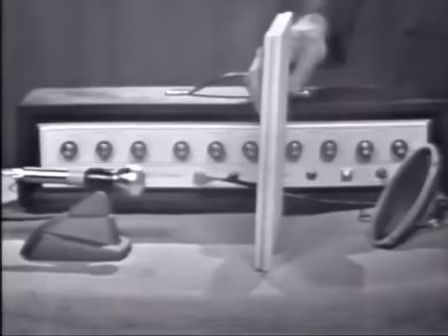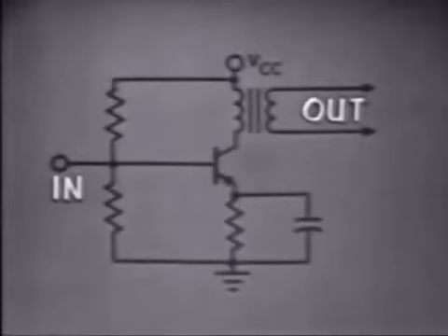Any amplifier will oscillate if feedback occurs. But what is the frequency of oscillation? In the LC circuit, we found that frequency is determined by L and C in the tank. Now, the same thing is true in the amplifier that oscillates. But since there is no frequency determining device, the frequency of oscillations is determined by distributed L and C. That is, the input capacitance of the amplifier, the inductance of the leads, or any inductors and capacitors in the circuit. Very difficult to predict the frequency.